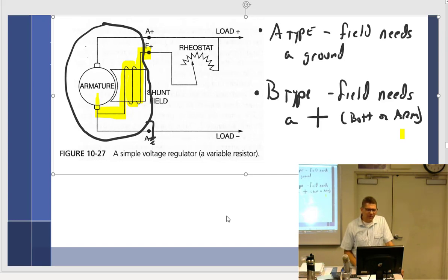So you're running 110 AC voltage through those field coils. What do you think that's going to do to the residual magnetism? Increase it? No, that tends to want to kill it. So you can kill it or inadvertently go backwards. The theory is if you have a generator that was just freshly overhauled and you get nothing out of it, well, number one, it means it wasn't tested, so don't call it an overhaul, but I digress. If you've killed off the residual magnetism and you go to run it, you're not going to get anything. So you have to do this thing called flashing the field.